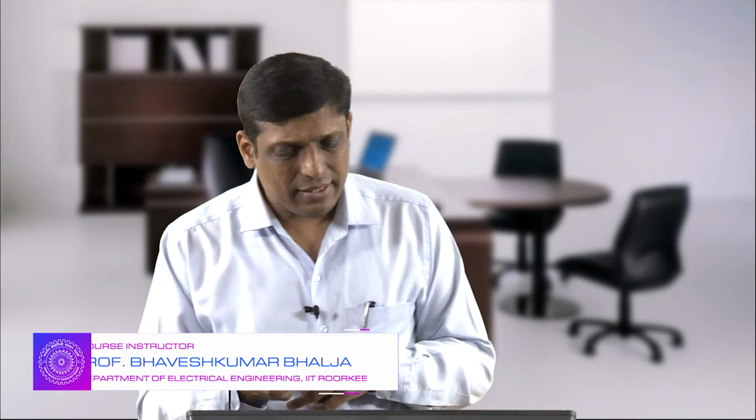And the last method is the averaging method, in which averaging of the different phases is carried out and then the final tripping is given. And then we discussed the overall block diagram of the digital relay, and if we consider the differential characteristic, then there is the IPU, slope 1, slope 2, and along with that 2 important additional settings, the high set differential trip and stabilization against heavy through fault, especially in case of CT saturation, that is provided by the relay manufacturer. Thank you.